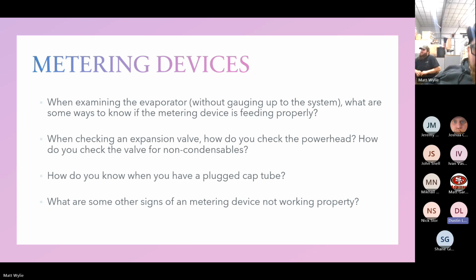So I would encourage, if you ever do have a case that has high superheat, to pull and check the screen and clean it before adjusting the valve. A week or two ago the valve was maybe running fine, so something obviously changed. It's not always the valve.